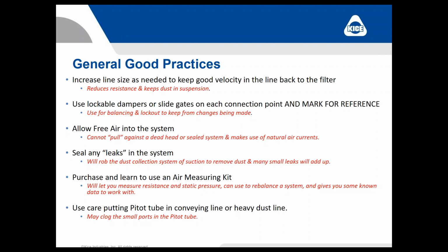Let's go back to that point. You've got to allow some free air. You can't pull against a closed system and get any kind of movement of air. So you've got to have some free air. You've got to make use of natural air currents. Seal up any leaks in the system. If you have enough points where air leaks out or air gets pulled in, you may not have enough air at the end to pull that dust through the line. And they'll add up.